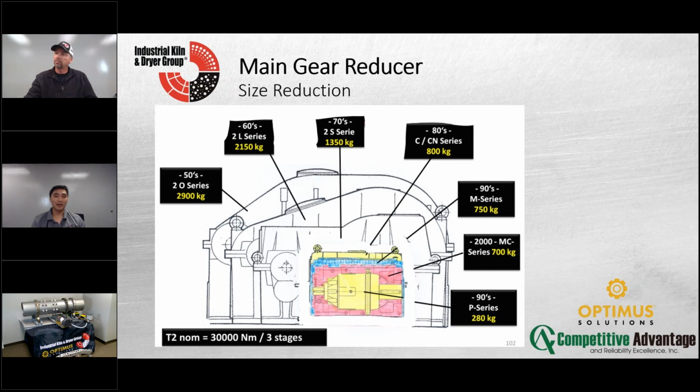But like I said, I know a lot of guys, they like to stick with the older stuff because maybe it's less moving parts or whatever it is. Well, also, if you can keep what you have, you don't have the modifications that are going to be required to go to a smaller gearbox. Maybe have the same location where the pinion hooks up to where it's a drop-in type of deal. But again, it's not really just a catalog system, right? It's not like, hey, I want this, install it. It takes a little bit of engineering. You've got to get a lot of information put together before you can go size a gearbox.